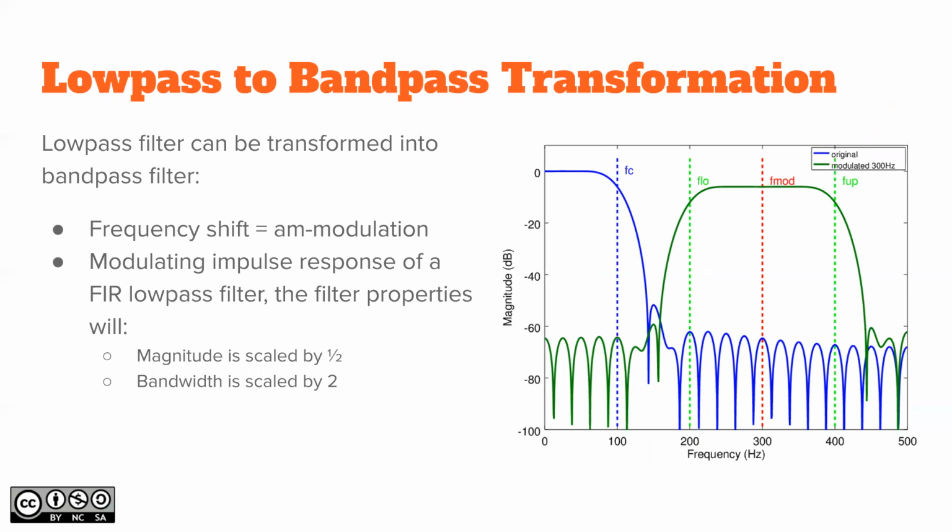How about having the bandpass filter then? Actually, that's again something that we can learn from math, and well, this has been engineering for a while. So frequency shift, AM modulation. If you want to transfer something on radio, the easiest way would be amplitude modulation, although then it's range dependent. So usually you use frequency modulation.